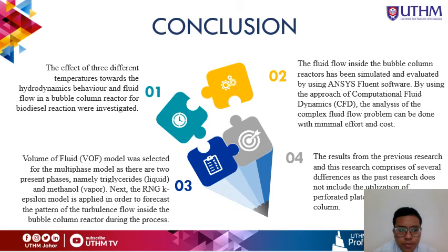And as for the setup, we have used volume of fluid model for the multi-phase model, and for the turbulence model, we choose the RNG K epsilon in order to forecast the pattern of the turbulence flow inside the bubble column reactor during the process. And also, we perform the validations.